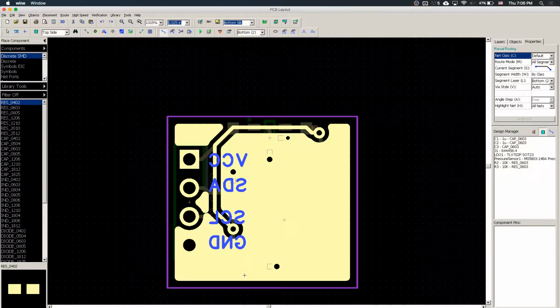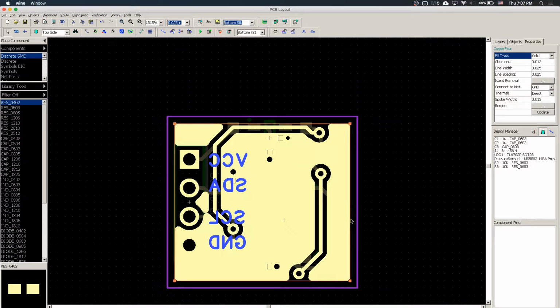Use the ground plane. Use of a ground plane will help with your noise immunity and allows the PCB to be more EMI resilient. And try to not have a loop in your ground, for example, a trace in between your ground plane like this. I'm going to demonstrate what I mean by that. Right now it's less of a loop, so I'm going to move it here. Now your ground plane has a loop around this trace, and if this hole gets bigger, you'll be more susceptible to noise, and it will make your ground plane very noisy, and that will sometimes induce really weird errors into your circuit that will be very hard to debug.